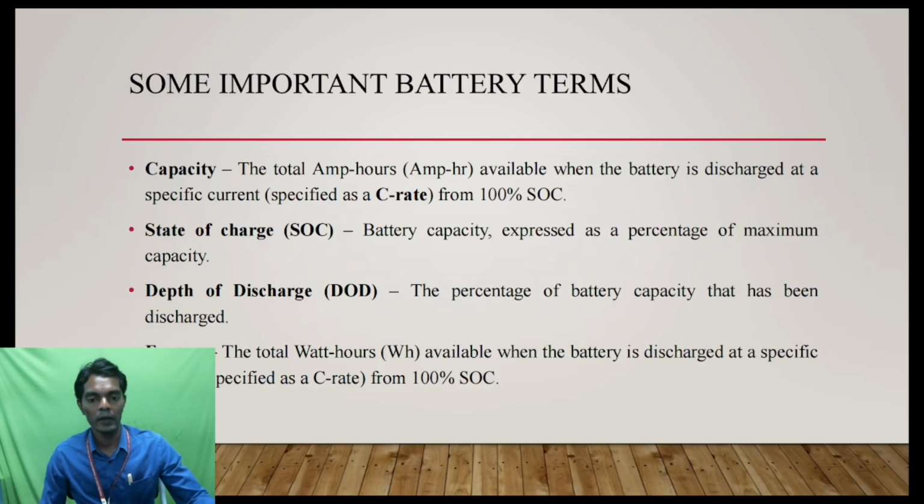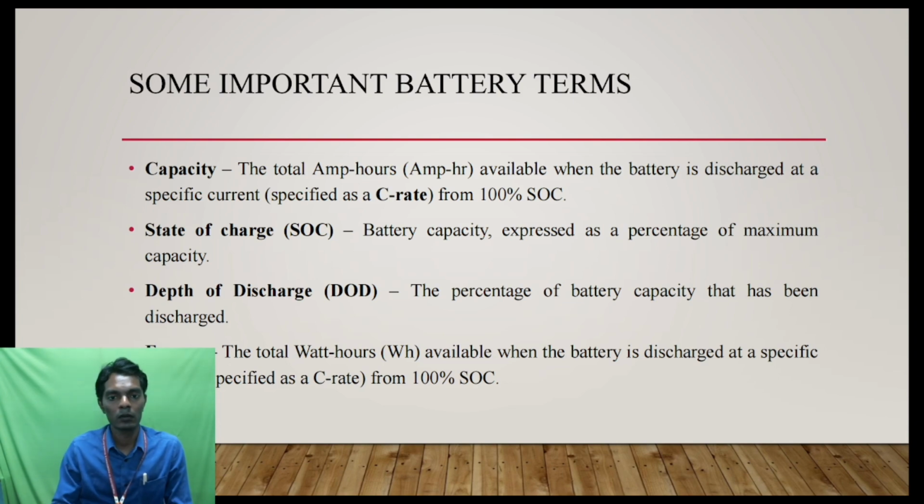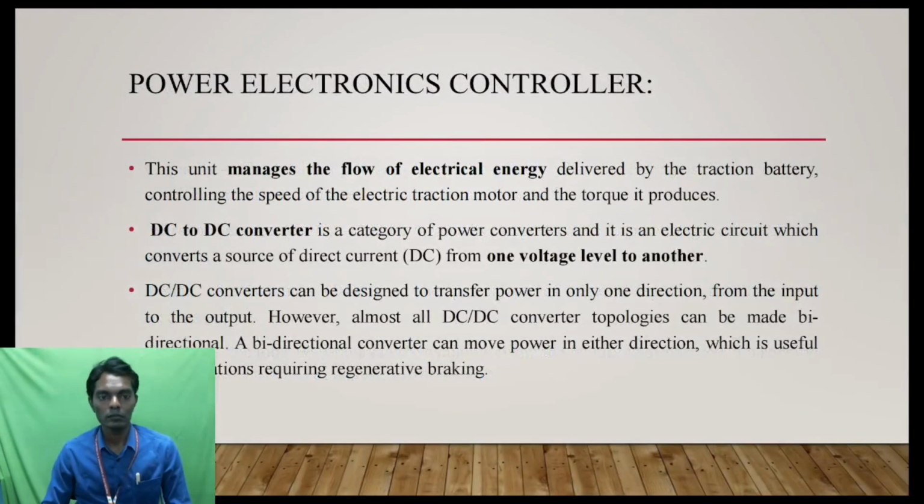So my battery can give 500 watt for 1 hour. I have a computer, let's say, and the computer rating is maybe 200 watt. So how long can I use this computer if I connect this battery? 2 hours. 1 hour is 200 watt, so 2 hours is 400 watt. So what is the energy? 400 watt hour. Right? Okay.